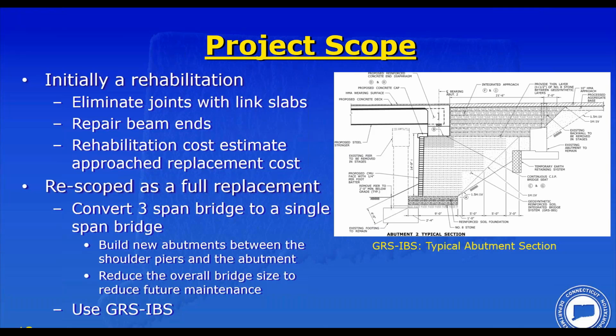But once you get away from the rivers in Connecticut, we have some very dense glacial tills, which are very conducive to shallow foundations. So in theory, you could build, and we have considered this, a pile supported footing, and then build the GRS on top of that. That could be done. But in this particular situation, we had quality soils, so shallow foundation worked.